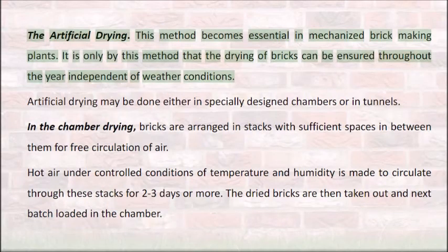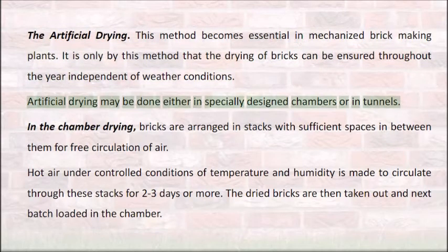The artificial drying. This method becomes essential in mechanized brick-making plants. It is only by this method that the drying of bricks can be ensured throughout the year independent of weather conditions. Artificial drying may be done either in specially designed chambers or in tunnels.